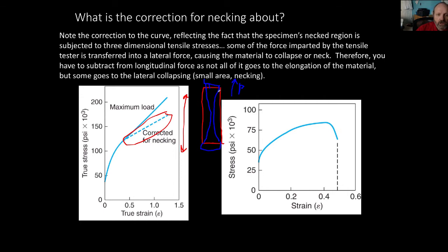Well, what's causing it to stretch? First of all, it's the load in the longitudinal direction, which is up and down. You've got a force pulling it, and you can flip it around, it doesn't matter. You're pulling it in the longitudinal direction, so that's why it's getting longer. But you've got to have some force that's lateral, a force that's causing it to neck, to shrink down. And you can't just create forces out of nothing. It's got to come from somewhere.